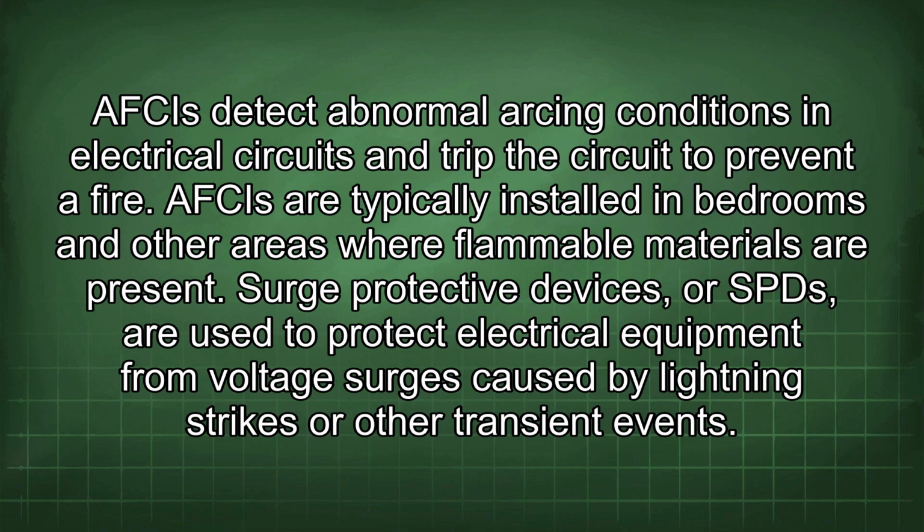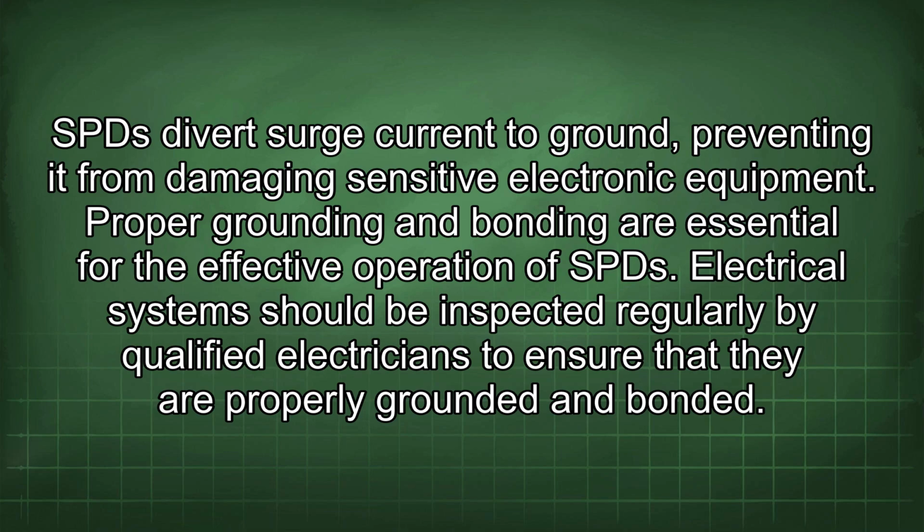Surge protective devices, or SPDs, are used to protect electrical equipment from voltage surges caused by lightning strikes or other transient events. SPDs divert surge current to ground, preventing it from damaging sensitive electronic equipment. Proper grounding and bonding are essential for the effective operation of SPDs.